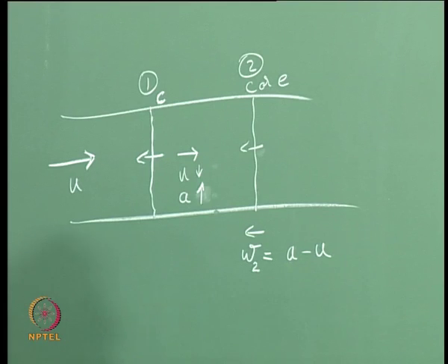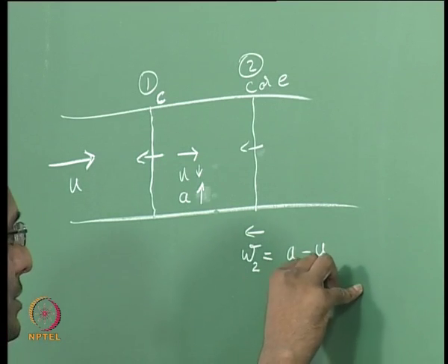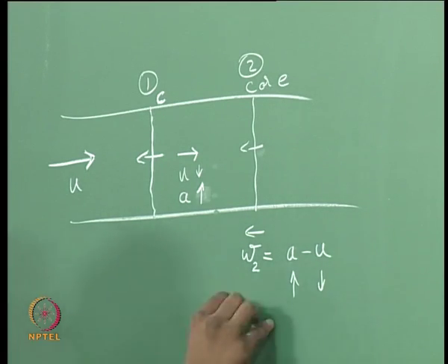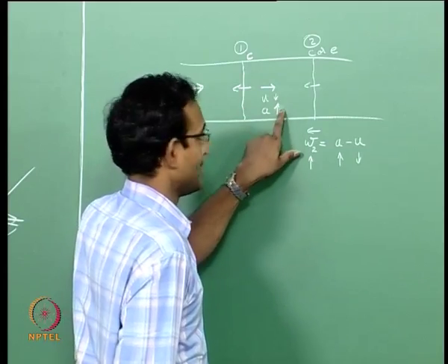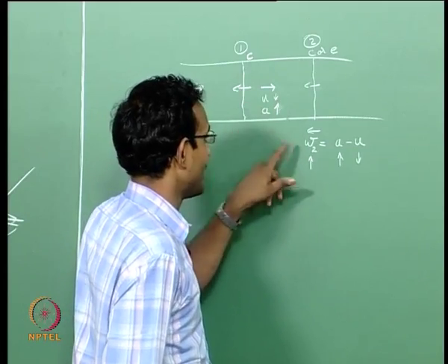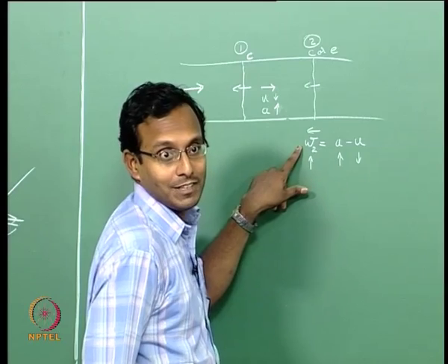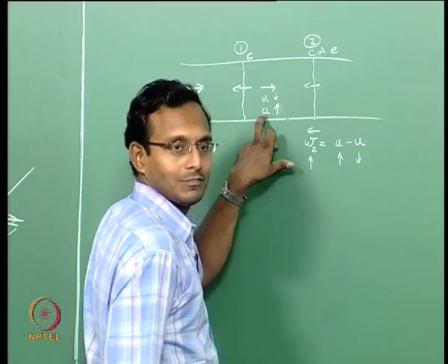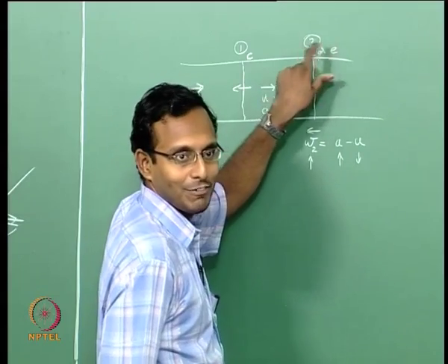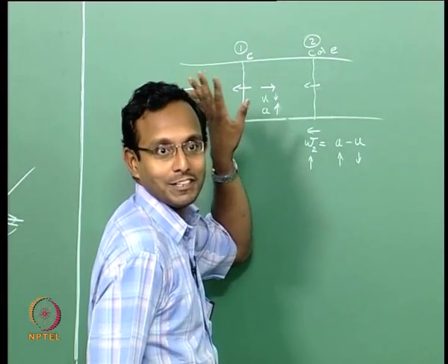Okay. If it is a minus u, a is increasing, u is decreasing, my W2 will increase. Okay. Because of this wave, I had these changes. So because of this wave, my second wave will travel faster. Originally I am going to say this wave will travel at speed of sound, because it is only a simple compression wave or a simple expansion wave, it is not a shock yet.